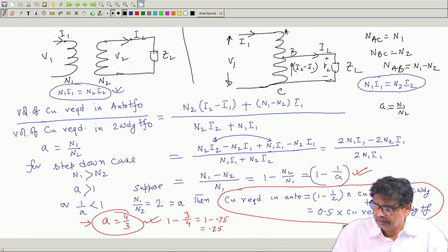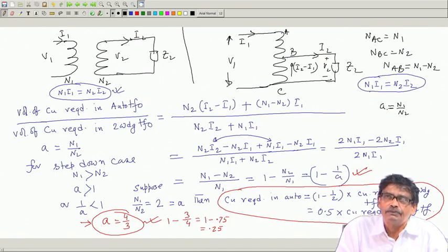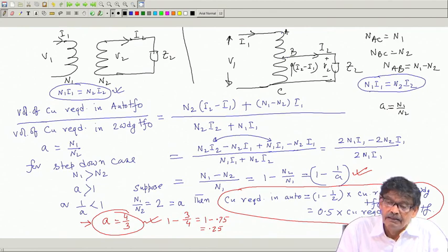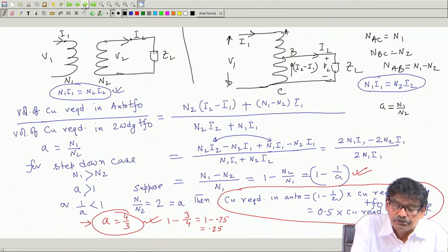Then we argued that if that be the case, then it should be only auto transformer all along. Two winding transformer should not be used. What is the fun? Because you will always be saving copper to transmit the same kVA from the source to the load side at two fixed different voltages. The same job can be done by an auto transformer, but there were further issues.